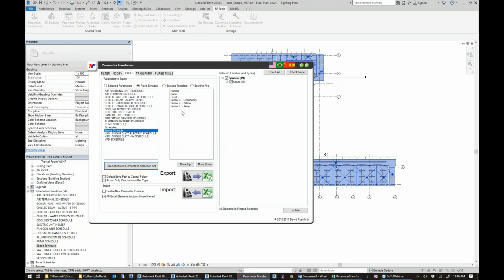And you can modify it in Excel where you can do formulas. Some people will export Revit data like room areas or different things to Excel. That way they can import it into maybe Trace or into some other calculation, voltage drop and short circuit calculation data. And they work on that data, and then they end with data in Excel, and then they can just import that data back into Revit. So you can use the Revit data to perform your calculations outside of Revit, and then you could bring that data back in. So it's accurate and it's based on Revit data.